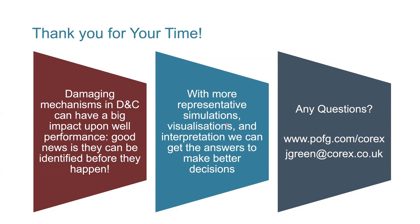Hassan asked, what is the difference of formation damage effects on carbonates and sandstone formations? So I suppose, I've hinted at it a little bit. It depends on whether we're talking about matrix or fracture in the carbonate world. In the sandstone clastic world, we're thinking about pore networks, what's in the pores, the minerals in the pores, do they clean up? The fluid in the rocks, does it interact with them? So we're looking at native minerals, clean up of the pores, clean up of the drilling fluids. And that's exactly the same in matrix carbonate production or injection, because again, we still have minerals there that we have compatibility issues with. We might not have clay or as much clay, but we still have native minerals.